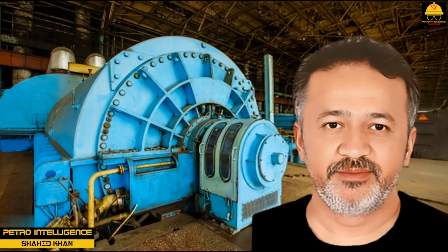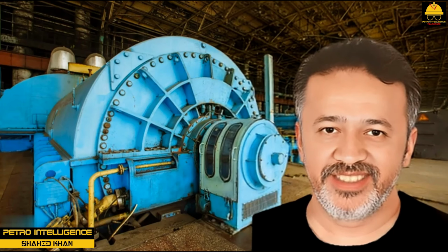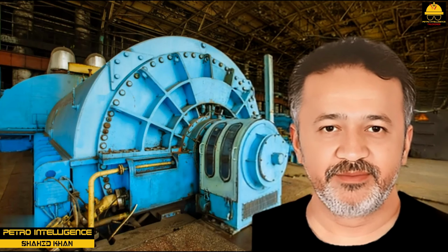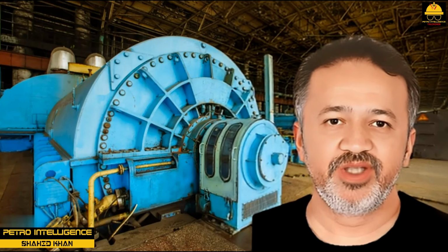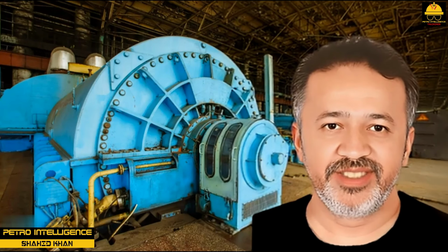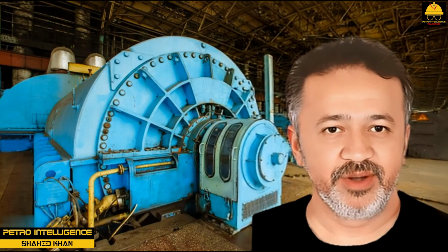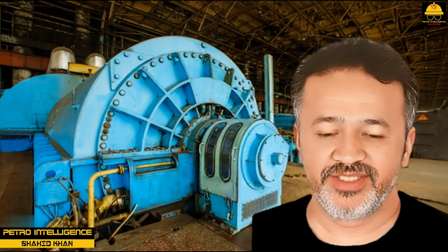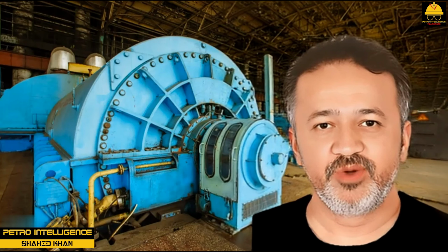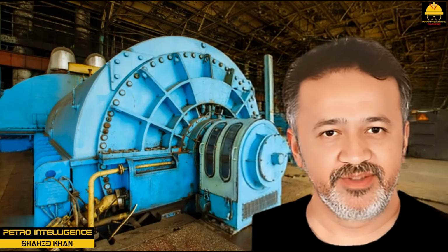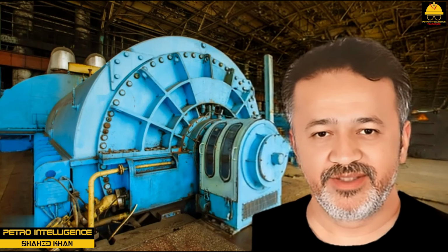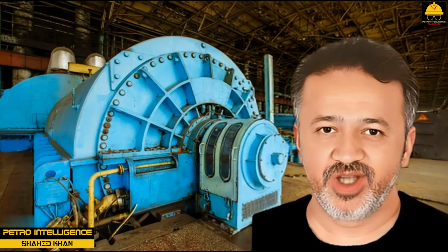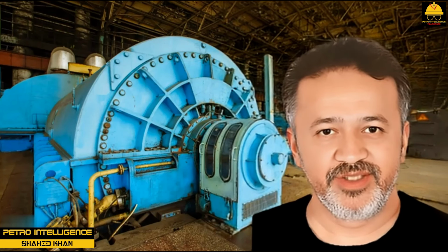Other parts. Steam turbines have a hand speed changer capable of making 10% speed range adjustments. A sentinel valve, a spring-loaded automatic relief valve, makes a high-pitched noise when turbine speed approaches the design maximum. An overspeed trip is a safety device used to shut down the turbine when it exceeds 115% rotational design limits. A weighted spring attached to the governor hub is used to close the governor and stop valves.